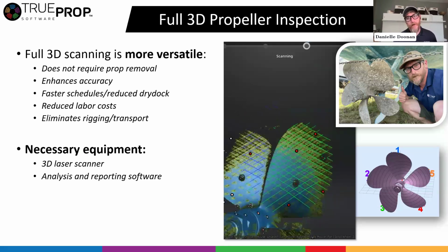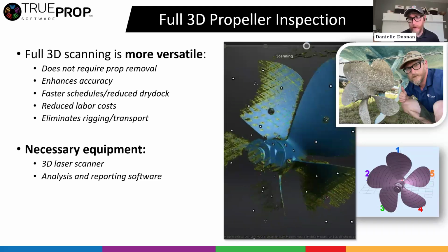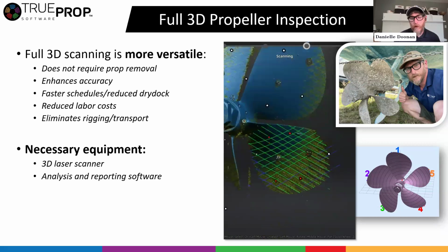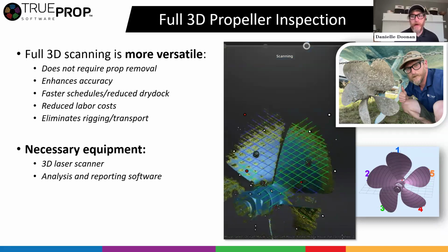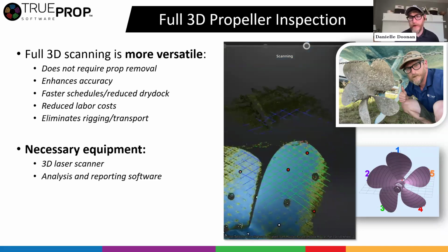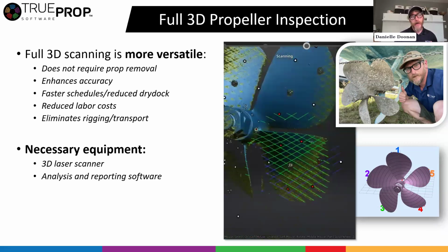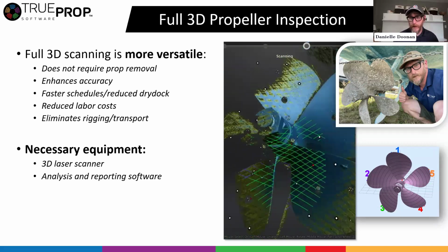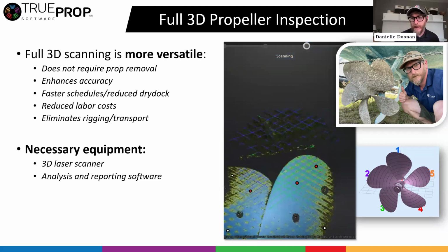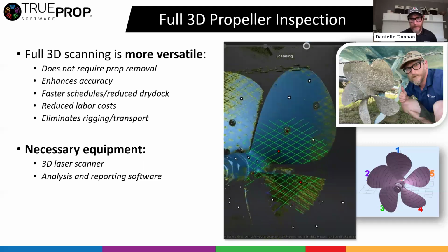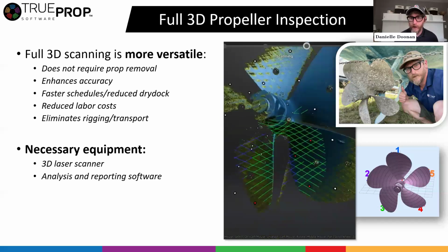And so now we offer a solution that can do that. It allows propellers to be inspected anywhere. What we're doing is leveraging commercial metrology equipment, such as handheld blue light scanners. That gives us a new versatile way to inspect the propeller without having to send it away to a specialist. In a scenario like a dry docking, we can check the propeller's condition without having to remove it at all. And in the case where a propeller needs to be replaced, we can capture the current geometry for building that replacement again by just visiting the ship itself.